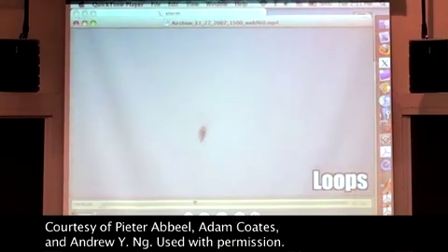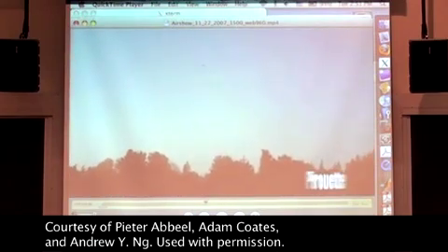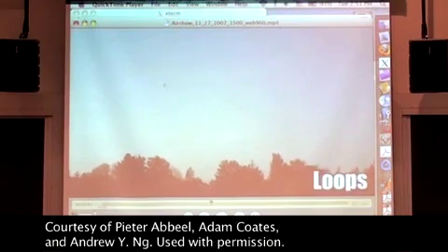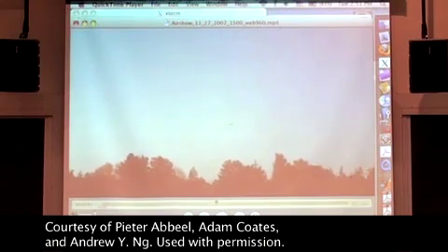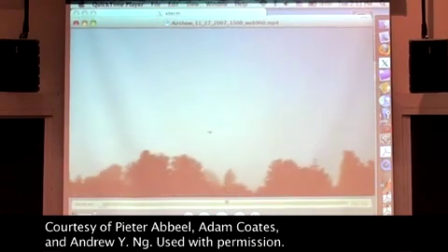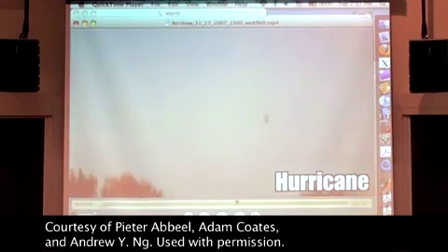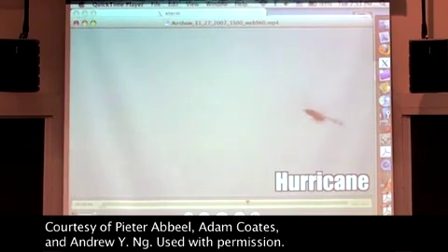So they do an iterative LQR controller design, and they decided that it's fast enough that they can do it 3 seconds into the future. So they're doing exactly this receding horizon thing, every dt, for that helicopter. They're doing iterative LQR to design a trajectory that's going to get me back to my pilot's trajectory.